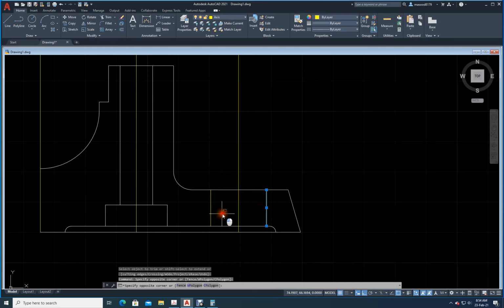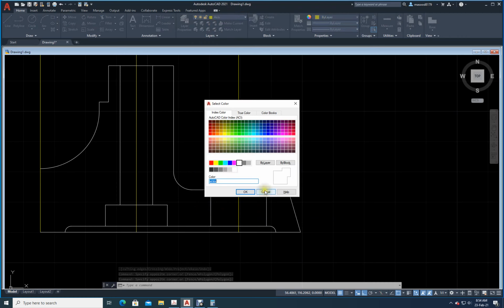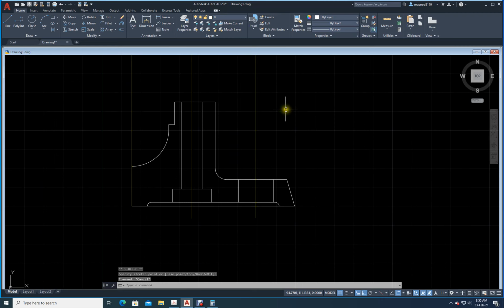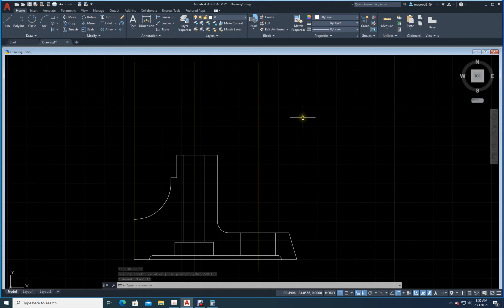Okay. Now what shall I do? Select this line and this line. Change the layer to what layer? 0 layer. Okay, we have changed it to 0 layer. Escape. Now see, everything is done. For this line I will click on this one and pull it out a little bit. Same thing with this also. I will hold on these grips and pull it out a little bit. Now the height is too much. I can always reduce it. Just pull it down.